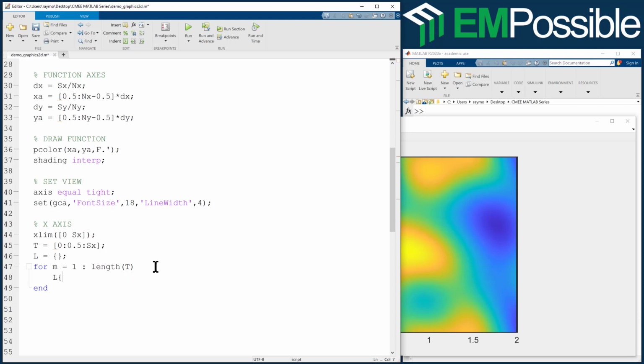All right, so for the mth string in this, we will use num2str. We give it the number, the mth value in t, and then we'll give it our ANSI formatting. So this will be number, point number: 1 decimal, 2 digits total, or 3 characters wide. Then we'll say set, get current axes, xtick, and we'll give it the tick marks, xticklabel, and we'll give it L.